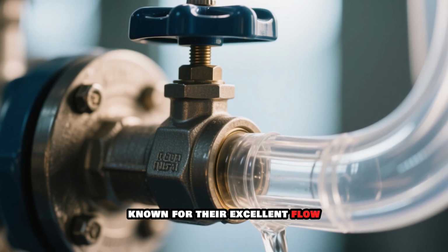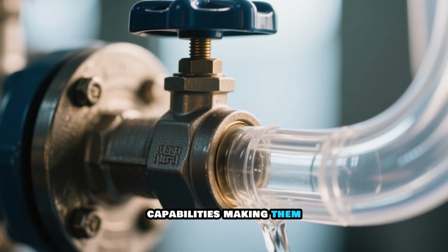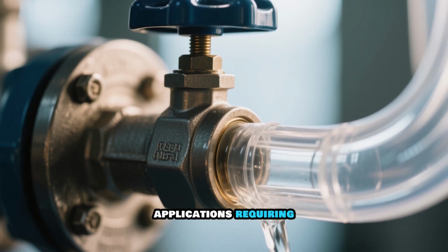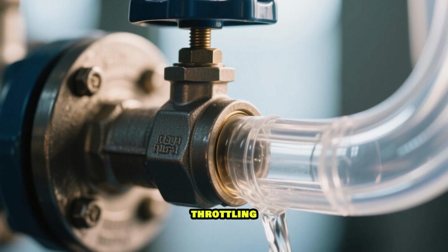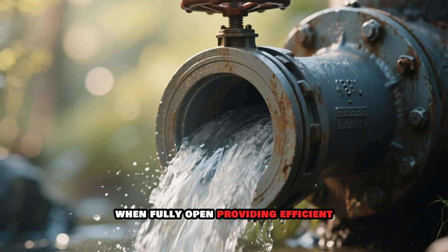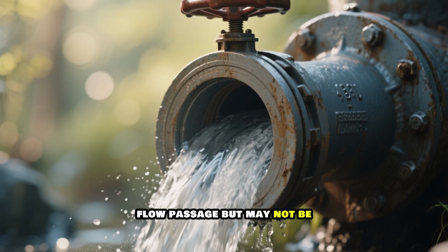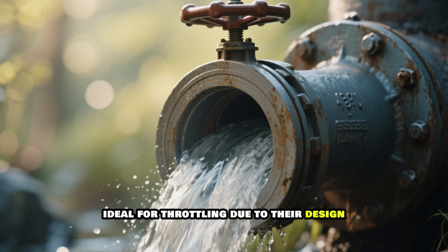Globe valves are known for their excellent flow characteristics and tight shut-off capabilities, making them suitable for applications requiring precise flow control and throttling. Gate valves offer minimal flow restriction when fully open, providing efficient flow passage, but may not be ideal for throttling due to their design.